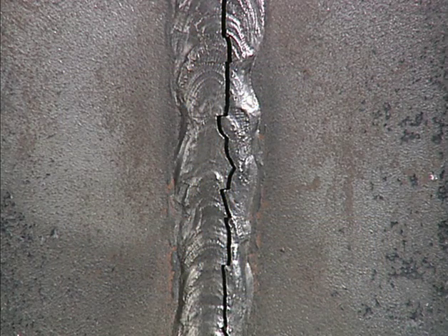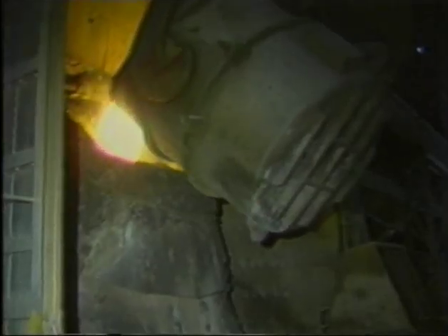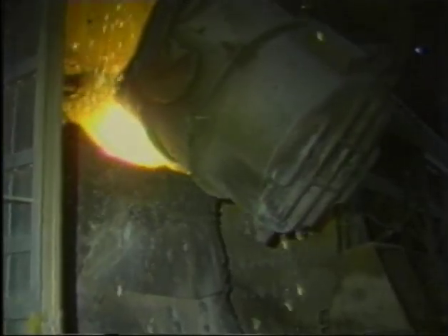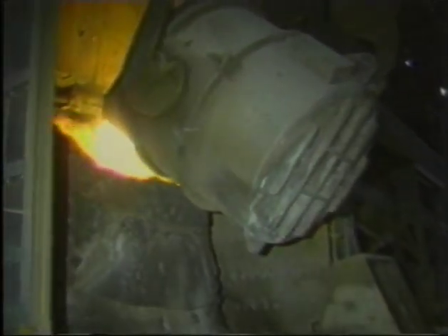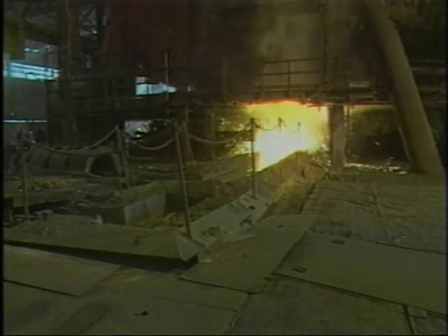We're going to look briefly at the reasons that distortion and cracking occur in steel, and those lie deep within its very structure. In its simplest form, steel is an alloy of iron and carbon. Carbon gives steel mechanical properties like hardness and strength, and it only takes a little carbon to do the trick. Most commonly welded steels contain up to 0.3% carbon by weight.